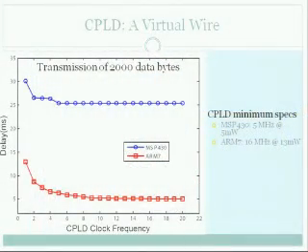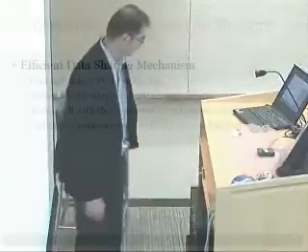And this can be more easily seen here, which is the run-reverse question that shows the effect of the clock frequency with respect to the end-to-end delay. Now, depending on the class of the processor we're using, there are specific sweet spots above which it does not make sense to increase the CPLD clock frequency. In the case of the MSP430 with 5 MHz, we're all set. The actual bottleneck becomes the processor and not the actual bus management. In the case of the ARM7, this has to be increased up to 16 MHz.